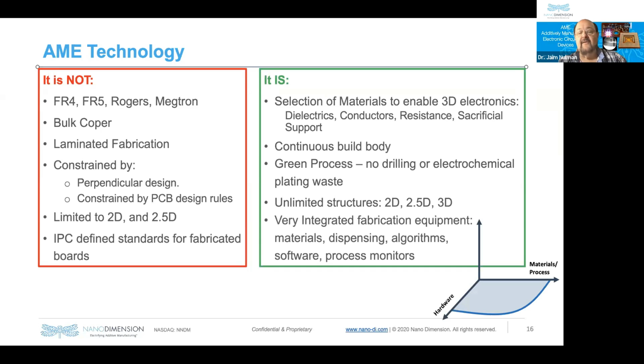However, it's a very integrated fabrication equipment between the materials, dispensing, algorithms, software, and process and monitors. Basically, for the deposition of these materials, especially the simultaneous ones, you need to synchronize all the components of the system so that you don't mix the two inks in the middle of the process. So you get very well-defined traces and insulating layers.